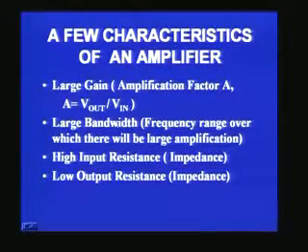Therefore an amplifier cannot, in principle, amplify all frequencies equally well. There are a few frequencies it will amplify very well. For certain other higher or lower frequencies, the amplifier will not be able to amplify. Therefore bandwidth is one characteristic which helps us judge how much an amplifier can amplify with reference to frequency range, and that is a very important thing. Usually our audio signals are from 20 hertz to 20 kilohertz, and therefore up to about 20,000 hertz the amplifier gain should almost remain constant. Then you find the bandwidth is very good for audio amplification. But there are situations where you want higher amplification factors for higher frequencies also. They are wideband and several other variations about which we will perhaps discuss a little more later on.